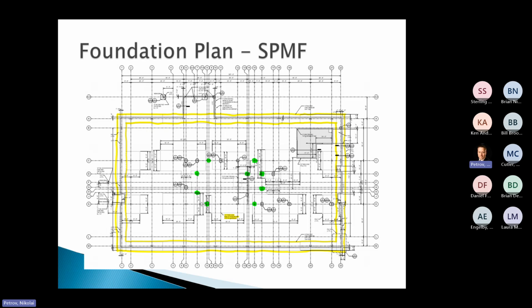Now, what about what's supporting the moment frames? The original construction, I think, had a 2-foot wide grade beam around the perimeter to support perimeter gravity columns. In the moment frame version, I was able to work with, I think, a 3-foot wide, 2-foot thick grade beam. So again, it's not really that much bigger than what's there. And it still is driven largely by gravity loading, not lateral loading, as opposed to the central mat foundation, which was obviously very heavily governed by lateral contribution.